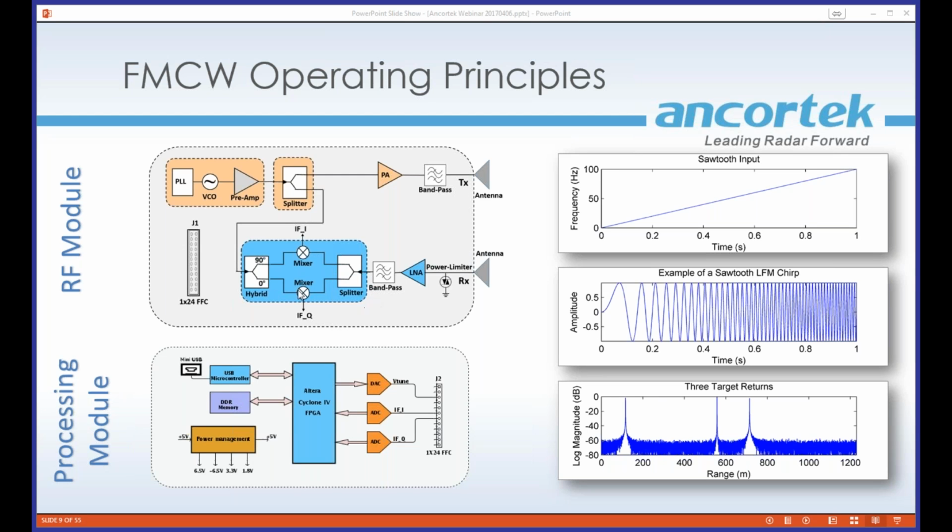what's going on is that those mixers are going to mix the transmit signal with the receive signal, and this is all done in hardware. This isn't done in software, so we don't actually offer control over that. So right now we actually have to transmit something. You can send out just a constant tone, but no, we can't do receive-only collections, just because of how we have the hardware set up.